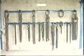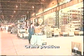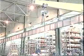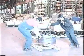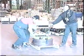Before attaching the load, the crane should be positioned directly above the load so as to avoid swinging the load as the lift is started. Likewise, when depositing a load, do not swing it to reach a location which is not under the unit. Cranes must not be used for side pulls or hoisting off vertical, as this could pull the winch rope out of position on the winch drum, causing damage to the rope.